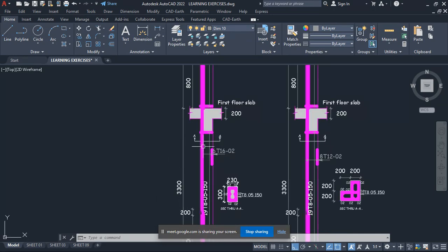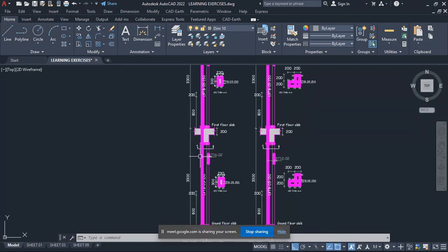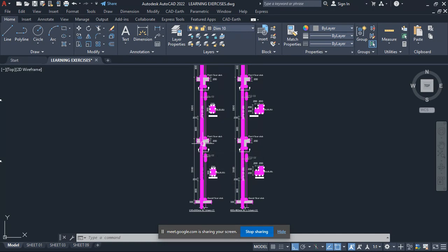You design each section, each floor separately, if you want to economize. It is not a rule of thumb that the bar size will be the same throughout. Sometimes you have like say 20 floors. So from ground floor to around 5 floors, you may have a different section of bars. Then from there you change, depending on your maximum moments and the actual loads around there.